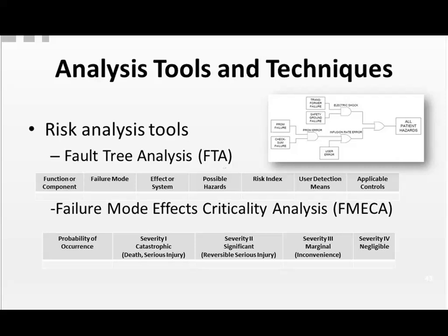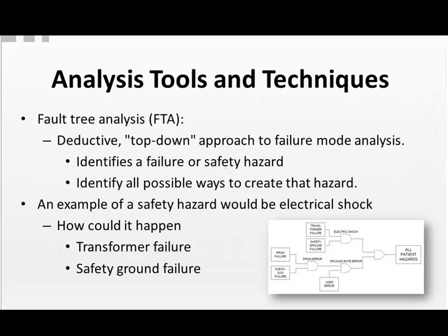That study is a bottom-up approach that's ideal for new or complex designs involving a number of processing steps. Now, a HAZOP is conducted on individual steps, each of which has a design intent. Now, a fault tree analysis is an effective top-down approach. The team starts with the undesired consequence or top event and identifies the initiating and contributing events that really must occur to produce it.